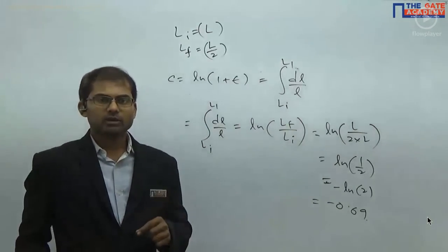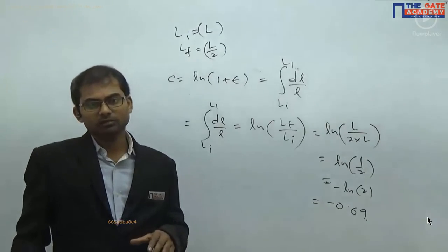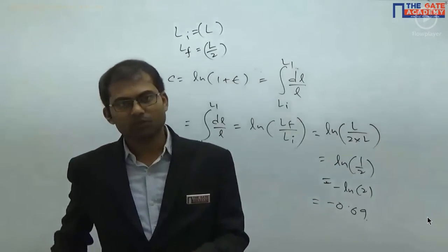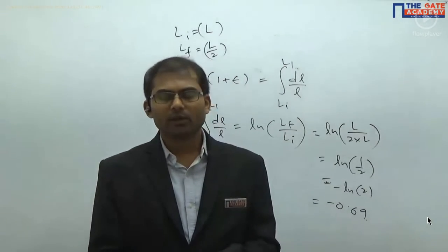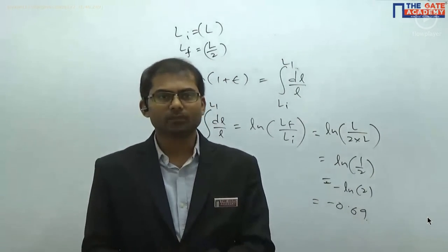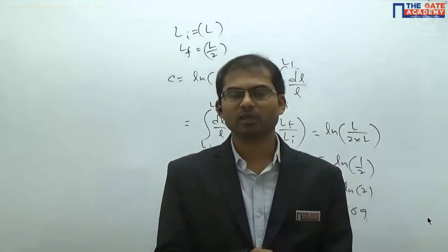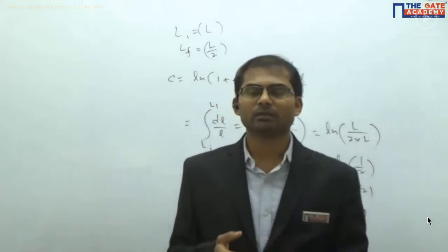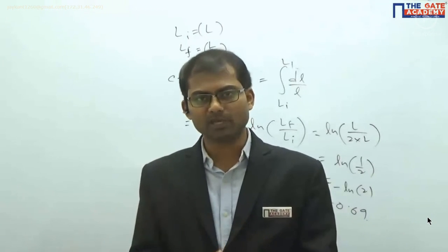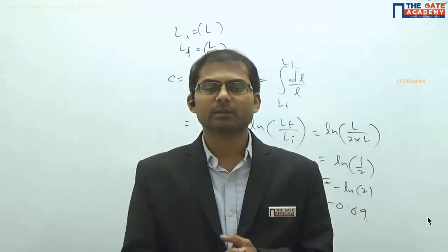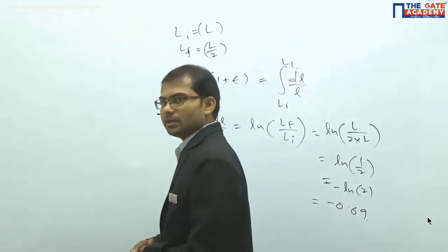One thing you have to remember: if they don't say whether to consider the material incompressible or not, by default you go with considering it as an incompressible material. For example, in this question, if you do not consider the material to be incompressible, then you would not get the answer as B. You have to consider it as an incompressible material, and only then will you get the answer. So the correct answer for this one is B.